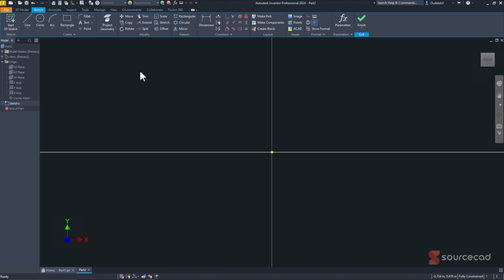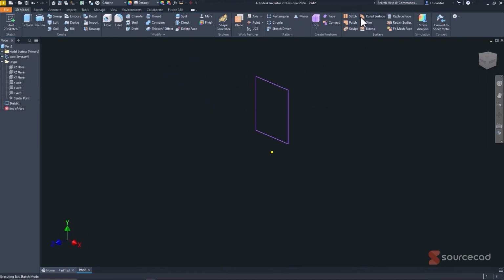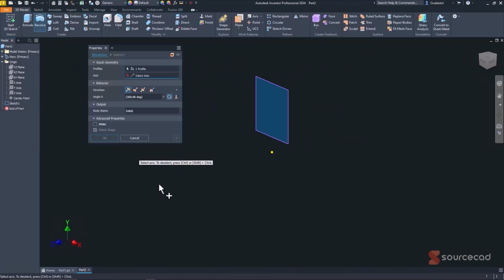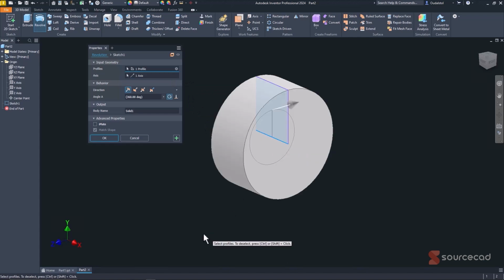And so when you do a revolve, you preferably want to do a center line. Now I'll just show you and be very, very simple. If I create a box, not even going to dimension at this point, I'm just going to click finish. I'm going to click revolve, and it doesn't understand what to do. That's because there's no defined center line, but it's asking for one, if you notice right here. So I can say this is my center line, and it does a revolve. And you can set angles and stuff. We'll get right back to that.